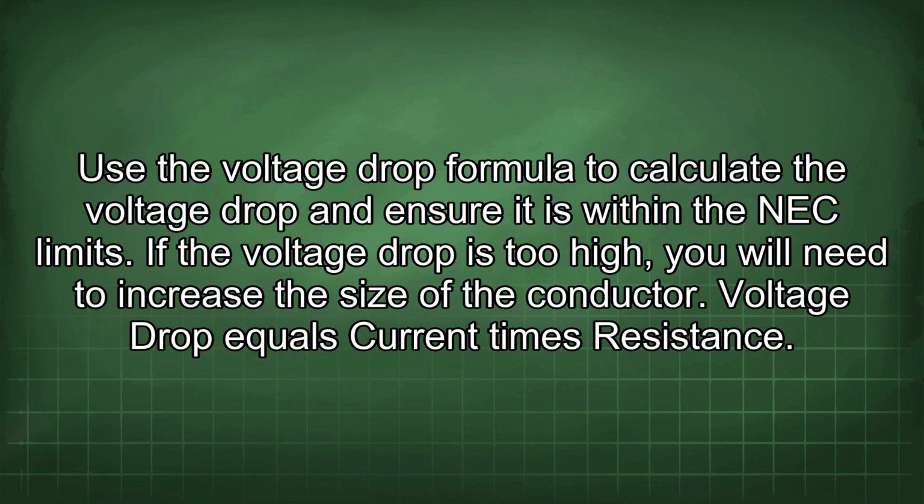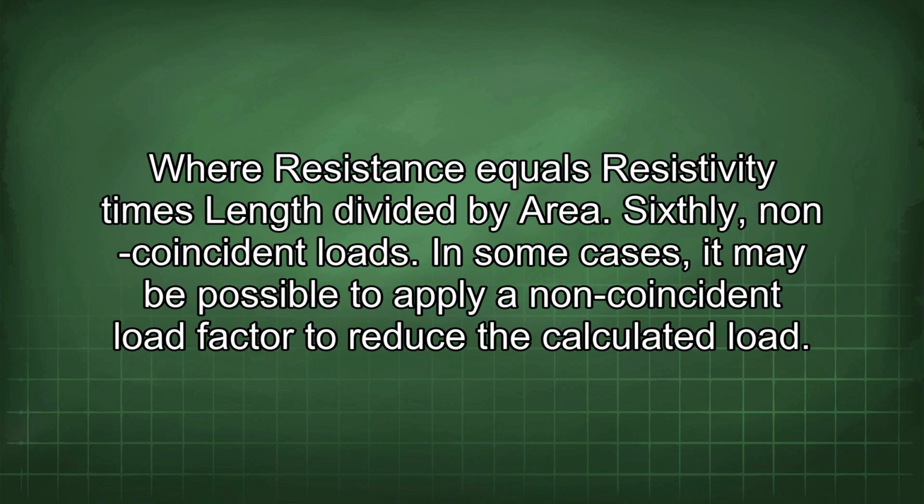If the voltage drop is too high, you will need to increase the size of the conductor. Voltage drop equals current times resistance, where resistance equals resistivity times length divided by area.